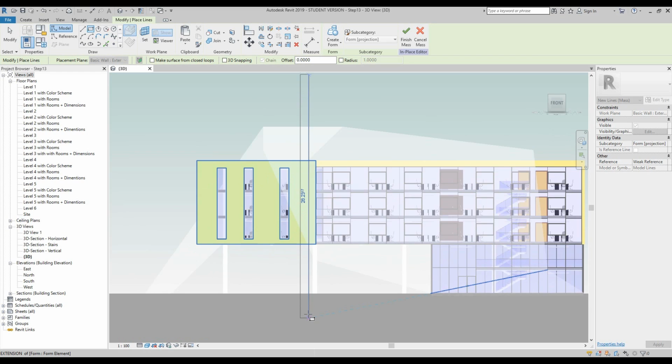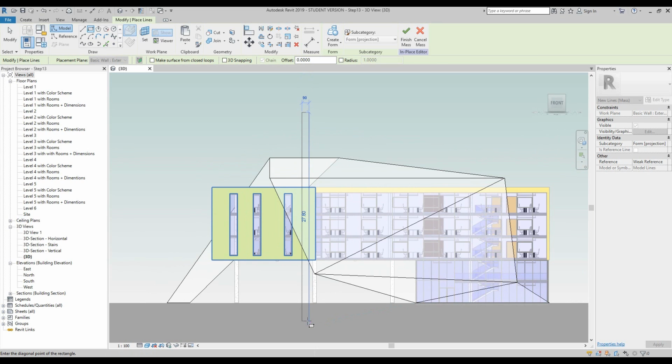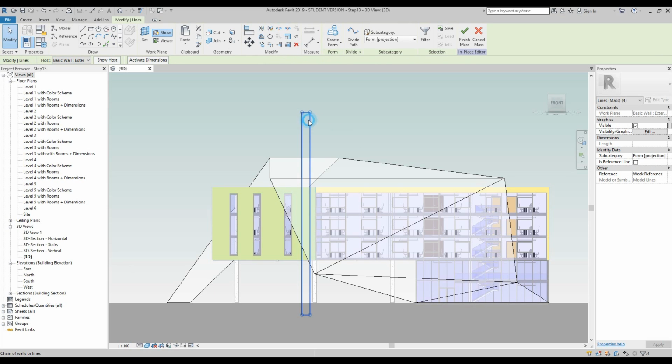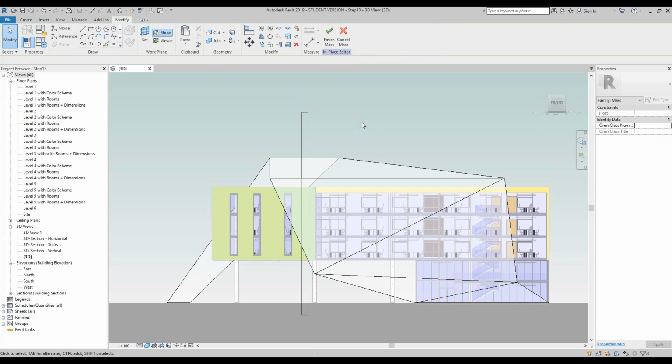and we want it to be about 80 centimeters. So if you can actually just manually get there. At the moment I'm getting 1, so if I select it, I can actually change it. Once you highlight this individual line your temporary dimensions arrive. So if I change this to 0.8, and then once I've done that, I'll press in negative space.